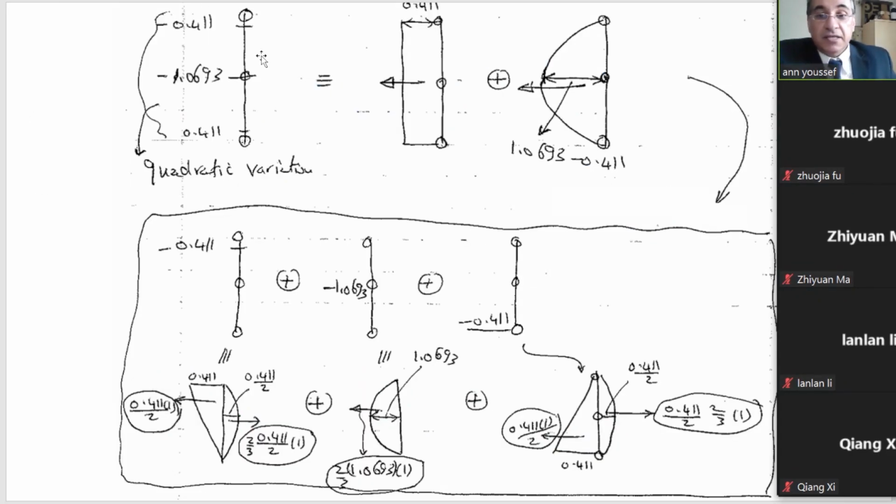You can see here, for this vertical element, I can compute the value in two ways. Either take this traction and this traction, both of which are the same, so we can put them as a rectangle like this one, and we take the difference between this value and this value to put it as a parabolic shape like this.